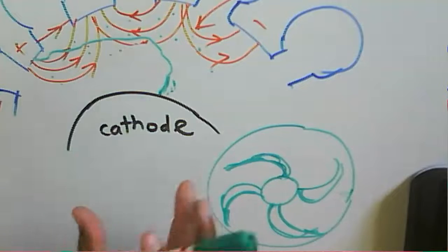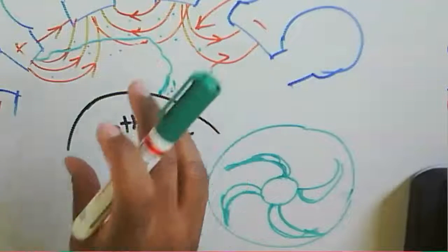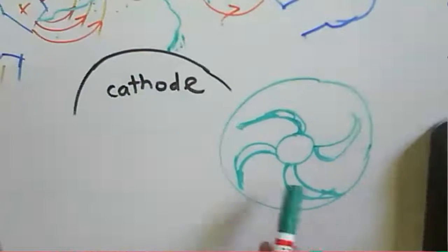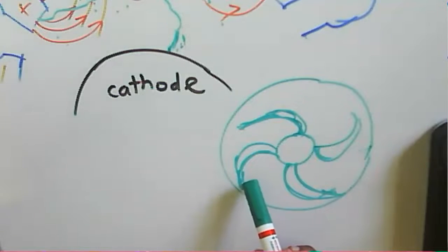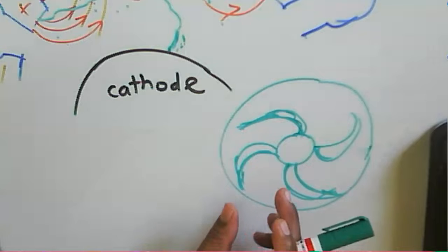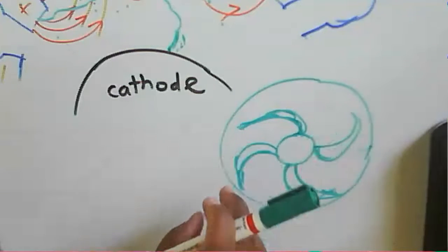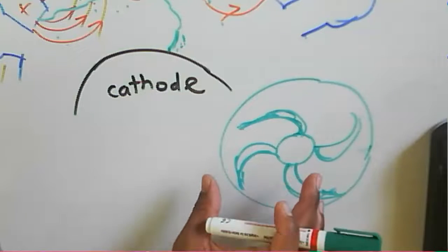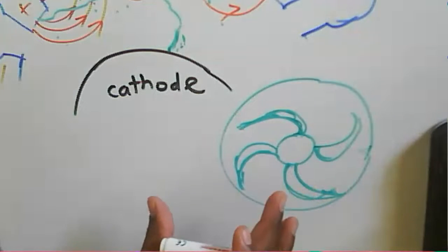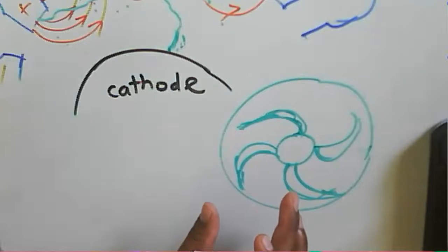Okay, because of that velocity modulation here, bunches of the electrons are formed likewise here. These are nothing but the bunches of the electrons, and they will reach this end here. So if you see the overall diagram, there will be a group of electrons, and that group of electrons is creating the spoke-shaped space charge. This is about a spoke-shaped space charge cloud of the electrons there.